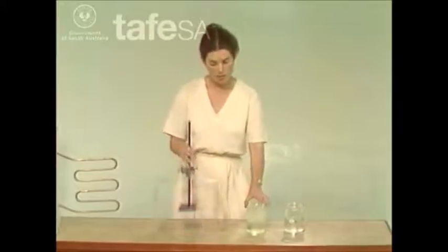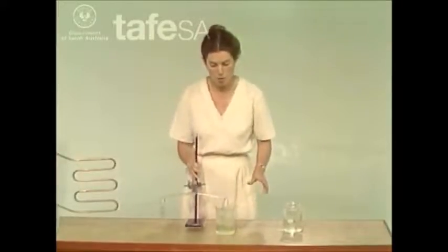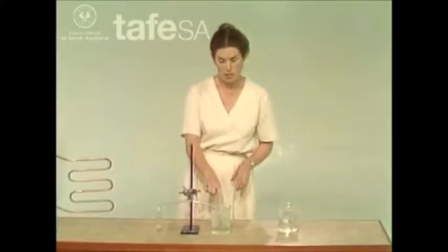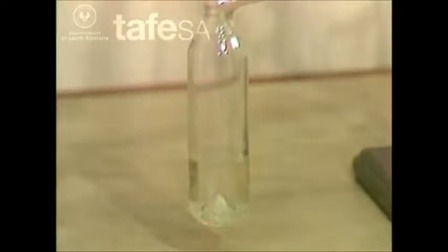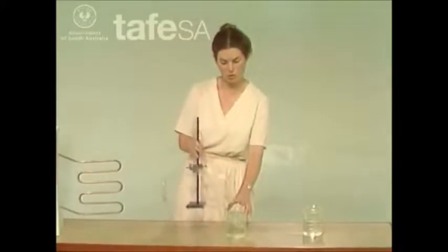If we remove latent heat from the vapor with this iced water, the refrigerant condenses, and the pressure drops because the vapor in here takes up less space. The reduced pressure allows the refrigerant to boil at a lower temperature, and we can see bubbles as vapor is released. If we remove the ice water,